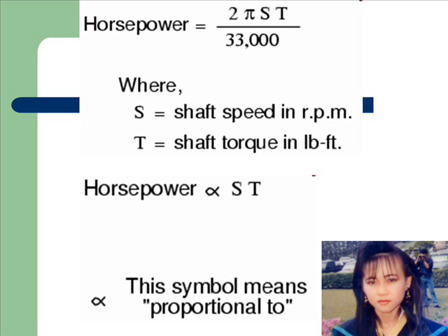Engine power is rated in a unit called horsepower, invented initially to rate steam engines. One horsepower is defined in British units as 550 ft-lbs of work per second of time. Speed of an engine's output shaft is measured in revolutions per minute, or RPM. Torque is the amount of twisting force produced by the engine, and it is usually measured in pound-feet, or lb-ft, not to be confused with foot-pounds. Neither speed nor torque alone is a measure of an engine's power.